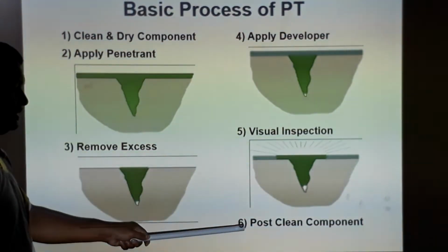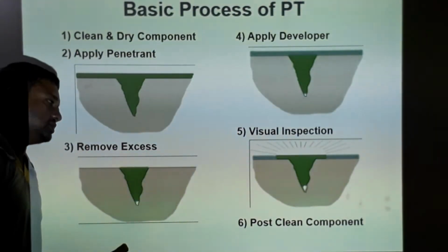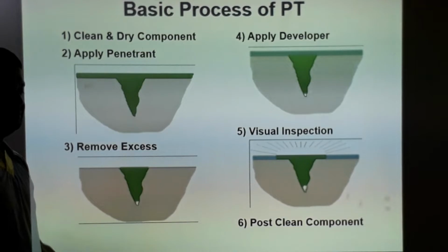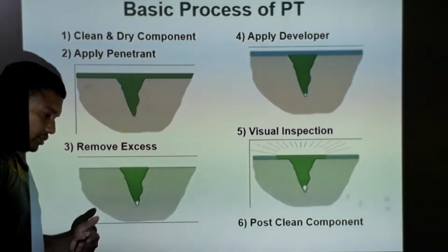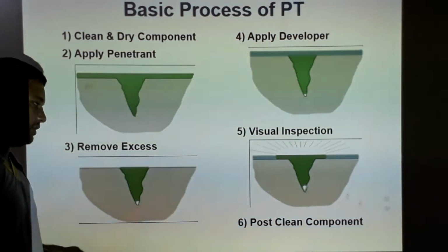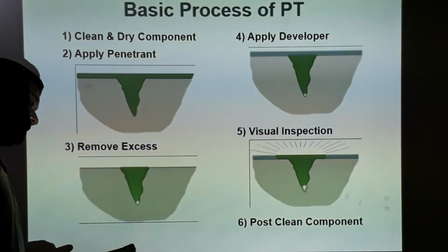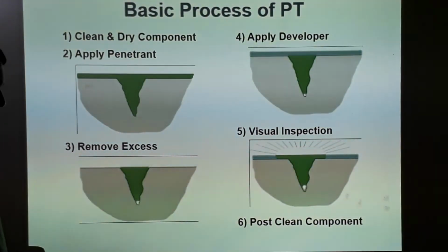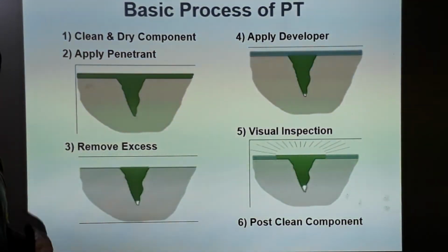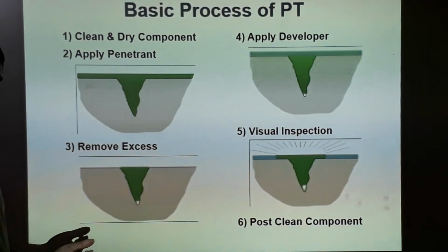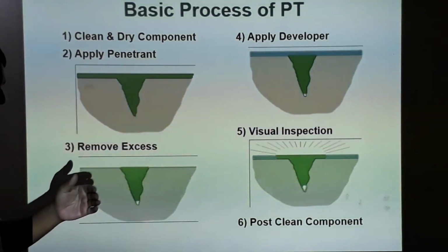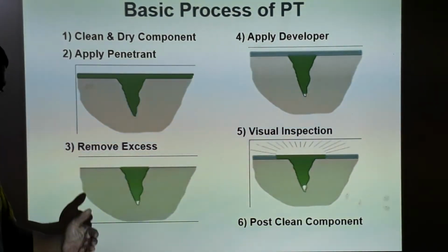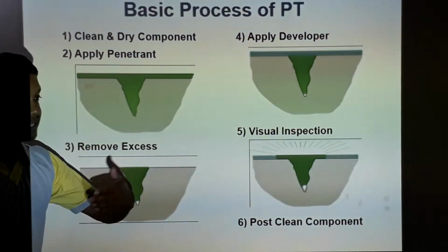Pre-cleaning is important and post-cleaning is important, because if you are not doing the post-cleaning religiously, or you are not doing it in a very thorough manner, or you are not following an effective post-cleaning method, then the residues of the penetrant material that remain inside the material due to ineffective post-cleaning may cause, and certainly cause, problems in the further functionality of the part, or in the part's next assignment.